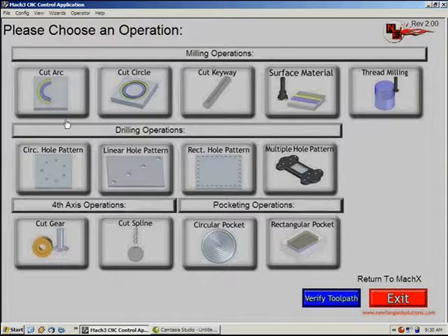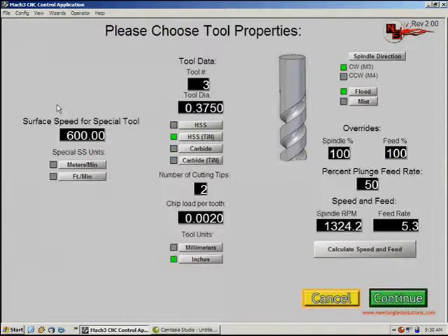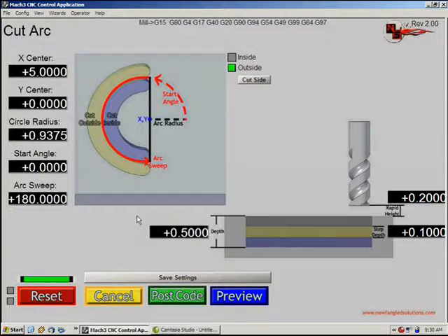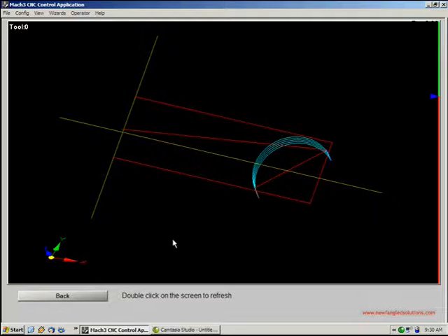But I just want to kind of give you a tour through the package and explain what some of the stuff is actually meant for after you've seen how it kind of functions. This one's very similar to cutting a circle. Mostly all the same parameters, where you have a sweep angle and a start angle. The sweep angle is incremental from where the start angle ends. So if we were to put this at 45 degrees, we'll start at 45 degrees and we'll sweep 180. Just like that. So we started here and swept this way.